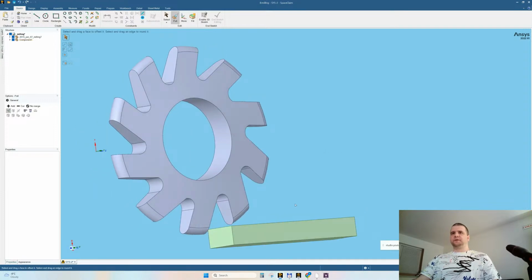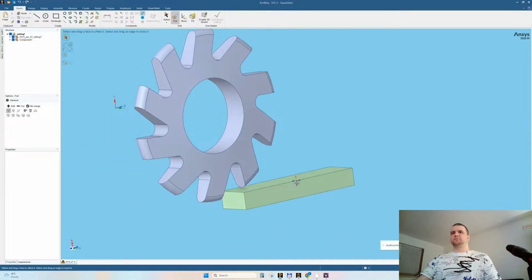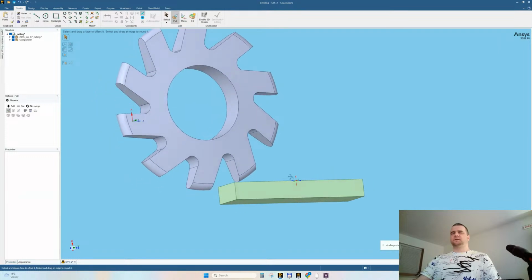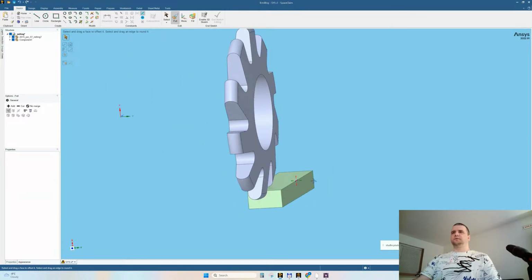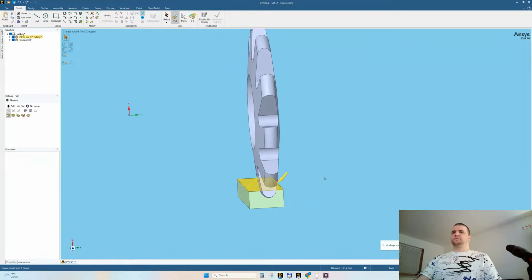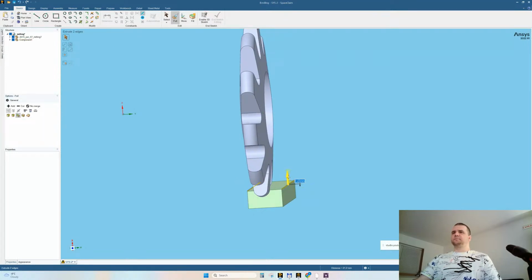So we were here. Are we doing something similar with what we had? You know, let's pretend we're doing something original. Let's just pretend a little. Click here, and we have extrude edge, and we will extrude these edges just a little. Something like this. 4 millimeters.